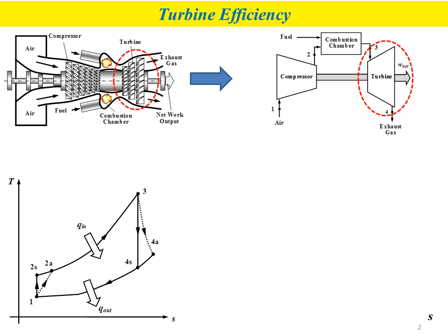First, the ideal case is represented by an isentropic process. For the turbine, the process starts from state number 3 to state number 4S. S represents the isentropic process, the ideal process. The actual process is represented by the process from state number 3 to state number 4A. Okay. So this is the expansion process in a turbine, for the actual and also the ideal case.